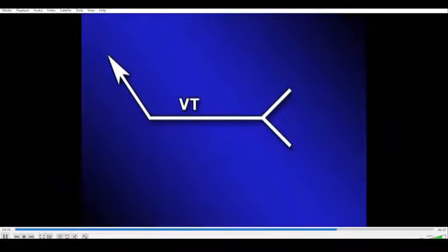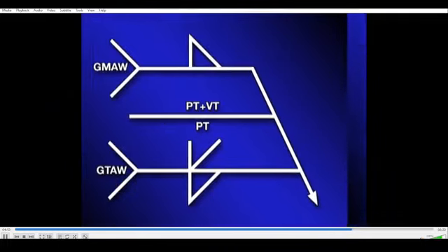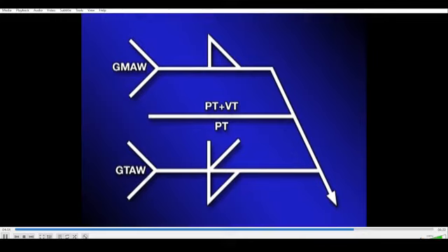When a test is to be applied on a specific section of weld, the section length is placed to the right of a symbol. If less than 100% of the length is to be inspected, this can also be specified by a percentage. In both cases, the required areas are usually specified in the written procedure. Non-destructive examination symbols can be combined with welding or other test symbols with the use of multiple reference lines.